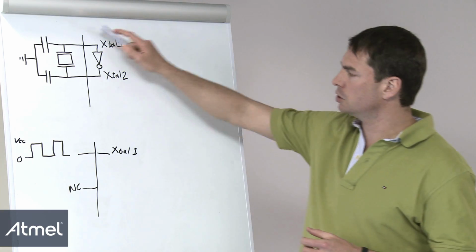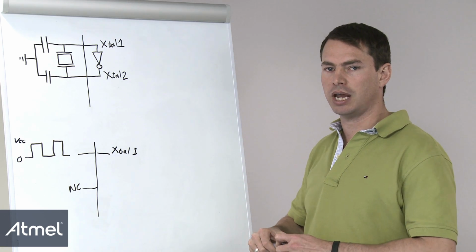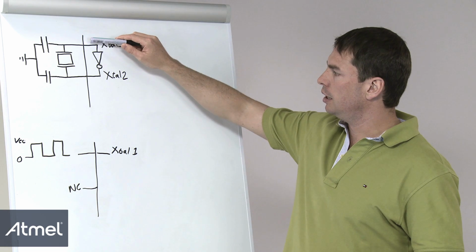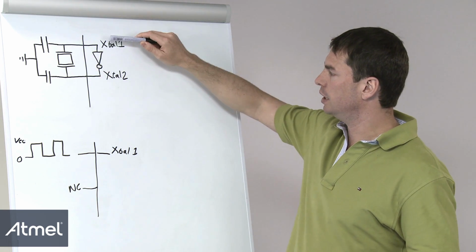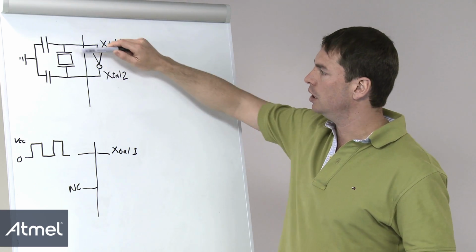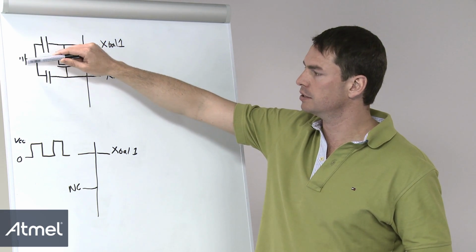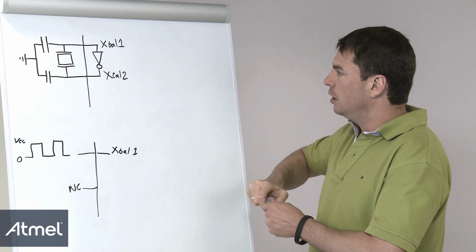We've drawn the situation of what happens when we use an external crystal. So we have a crystal connected between XTAL 1 and 2 pins on our board with two equivalent balancing load capacitors nicely grounded.